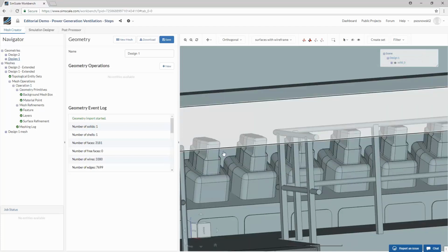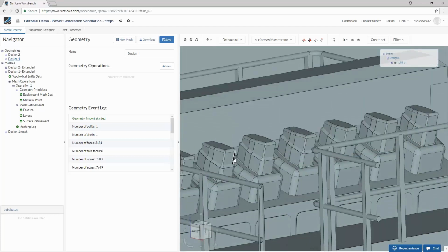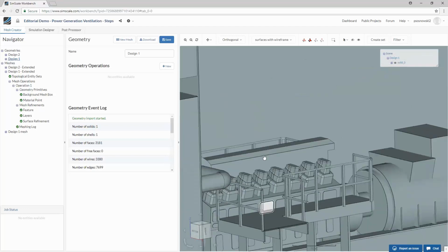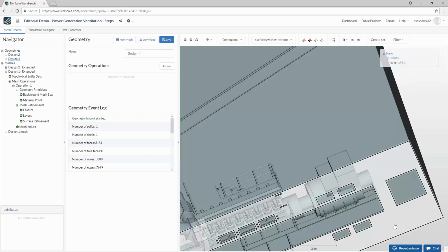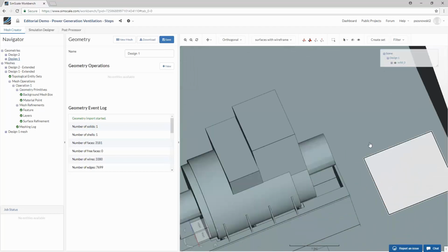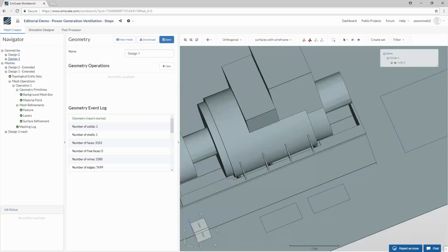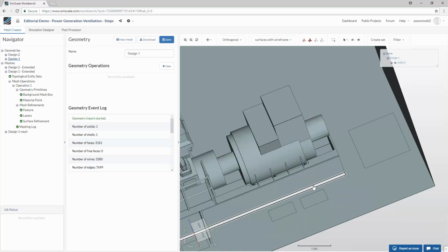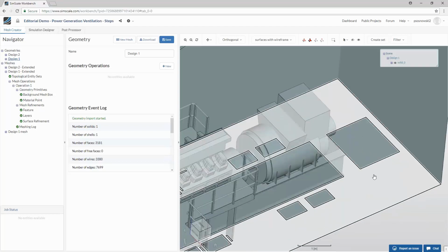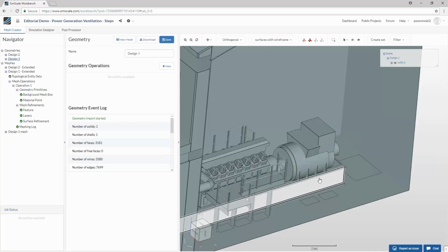It is not strictly necessary to use this kind of refinement. You could also get reasonably good behavior if you use surface refinements. For some particular applications, you would go with a feature refinement, for example, to make sure that your tiles are properly represented, you need a feature refinement. So yeah, there's a reason, but it's not strictly necessary. You can get a very good simulation without dealing with it.